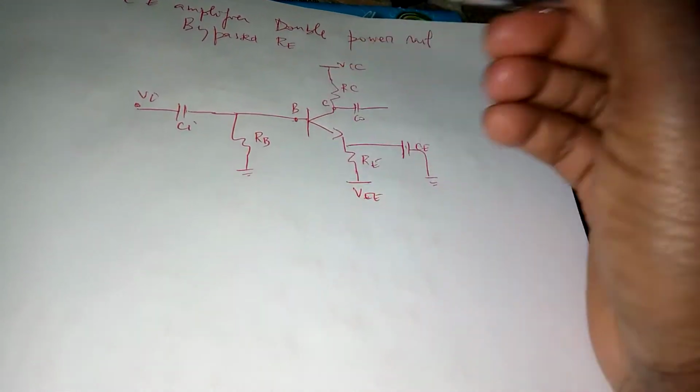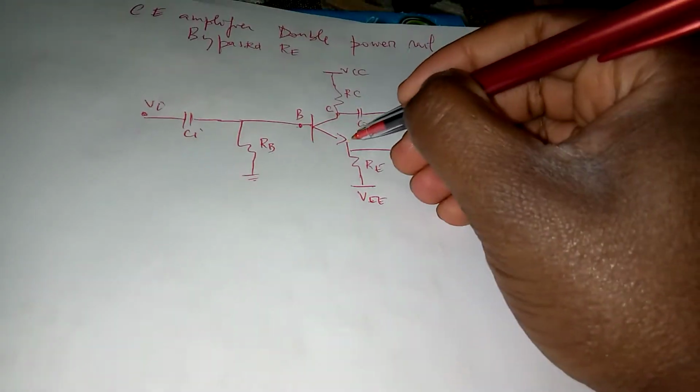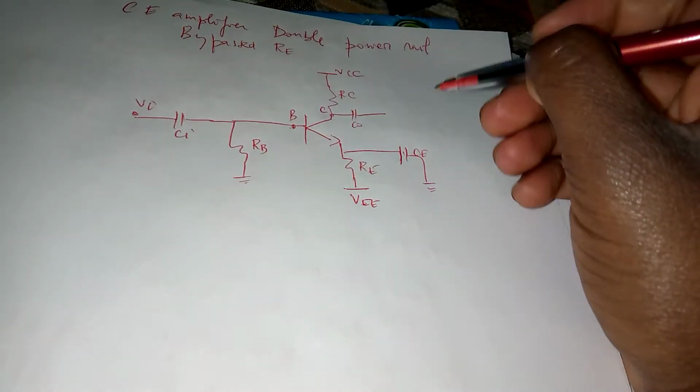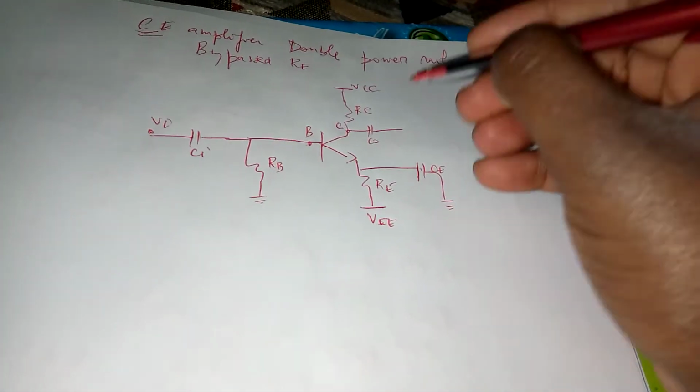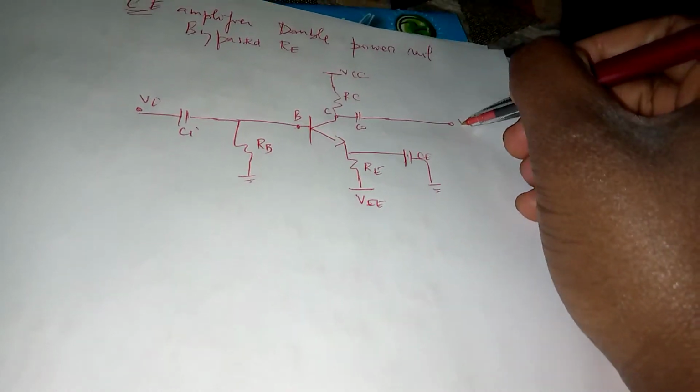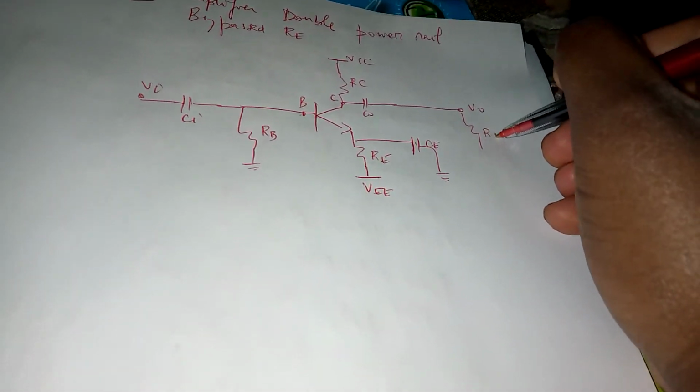The input is coming through the amplifier through the base, and we observe everything from the emitter. That's what makes it common emitter. And the output is taken from the V out. It could be applied to an RL, it could be loaded. The input side could also be loaded through RS and a voltage source VS.